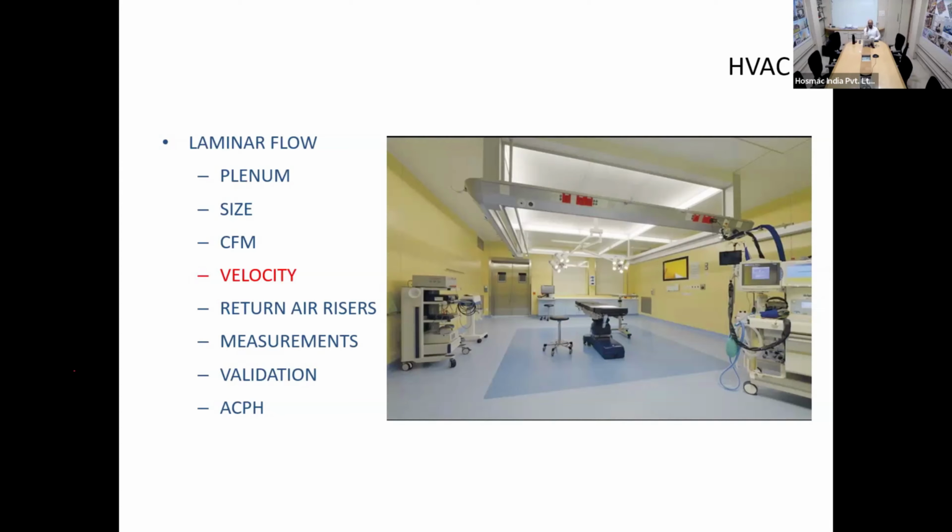So you have particles in air which are not visible to the eye because they're very small. But with this kind of filtration system, with HEPA filters, and this kind of velocity of air, the idea is that you push those particulate matter down and away from the surgical site, right? This is how you maintain aseptic conditions in the place where you're cutting open the patient for deep wound surgeries.